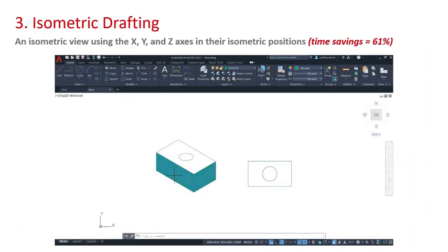So you can see there on the left, that is purely 2D drafting. There's a hatch pattern and there's some lines representing what looks like a rectangular base with a hole in it, and that's the ellipse that I mentioned. Now, if I start looking at IsoDraft there and switching on the status bar, can you see I'm changing the positions of the axes on the cursor, and that basically works in an orthogonal kind of setting, because it ties you down to drawing lines at those angles in the IsoDraft to allow you to create that 2D representation of that isometric view of the base.